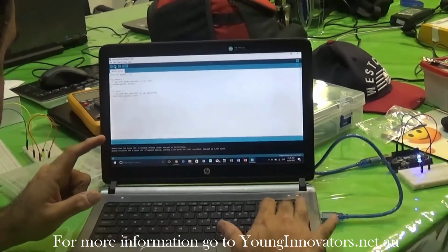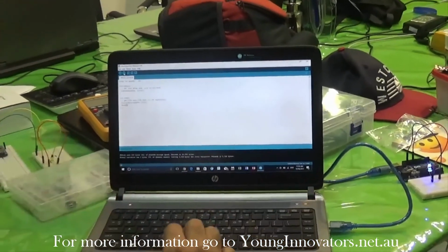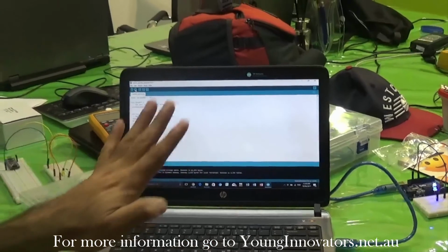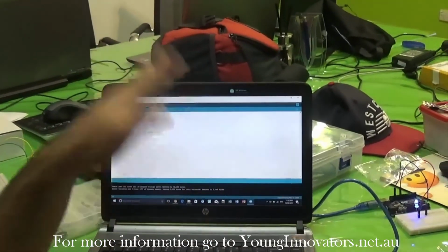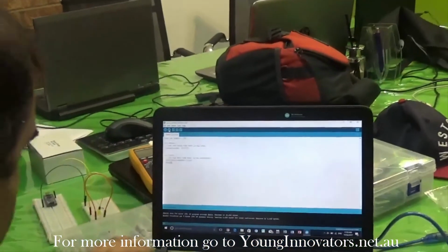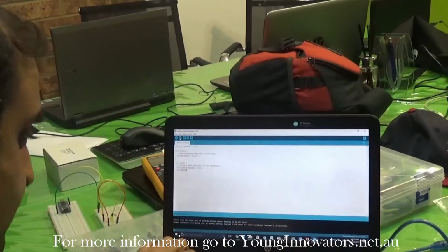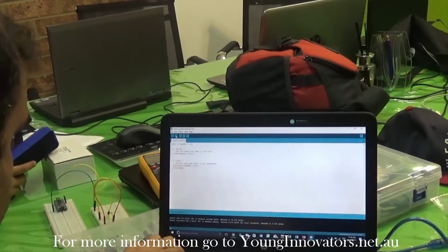Okay. Now let's do some delays. So you remember we need to do some blinking, right? So we'll say, okay, keep it up for 5 seconds, then turn it off for 5 seconds, then turn it on for 5 seconds. So that sort of loop, right? So this works in milliseconds. So 5,000 milliseconds delay,